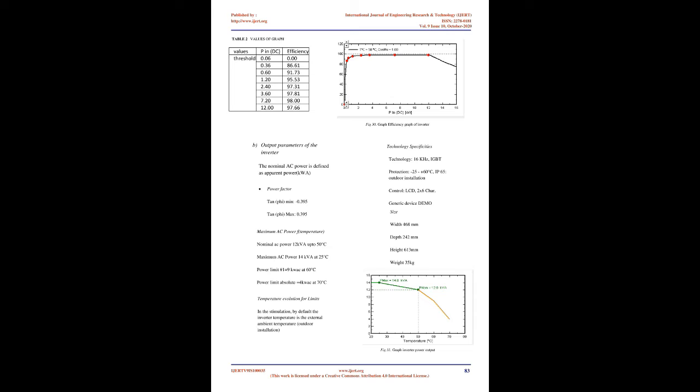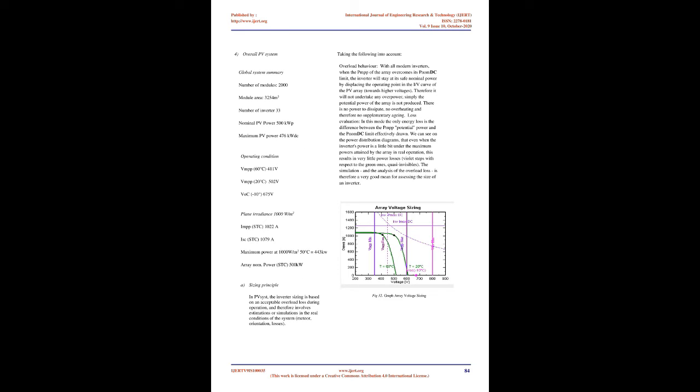A. Sizing principle. In PVsyst, the inverter sizing is based on an acceptable overload loss during operation, and therefore involves estimations or simulations in the real conditions of the system, meteo, orientation, losses. Taking the following into account.